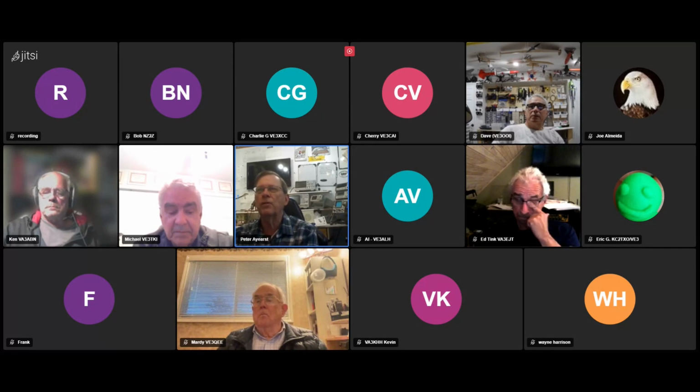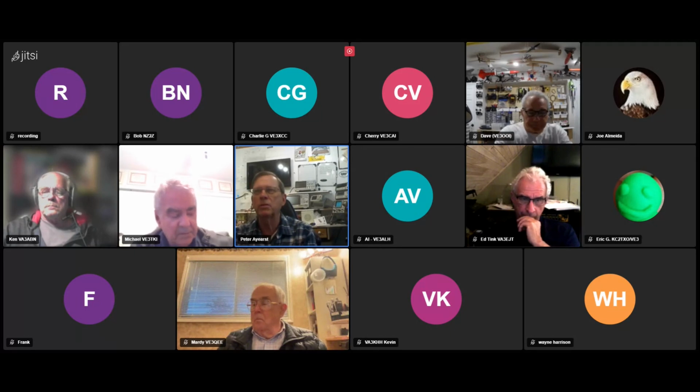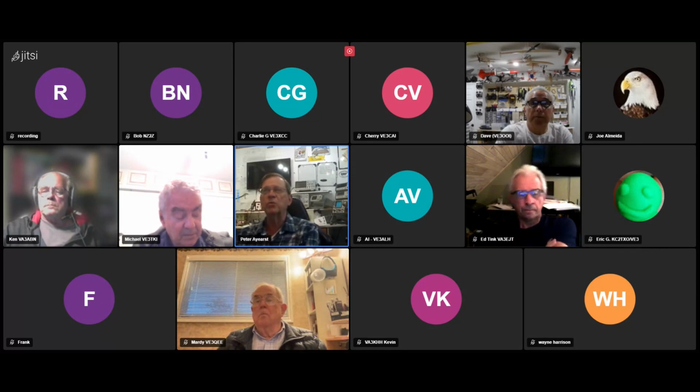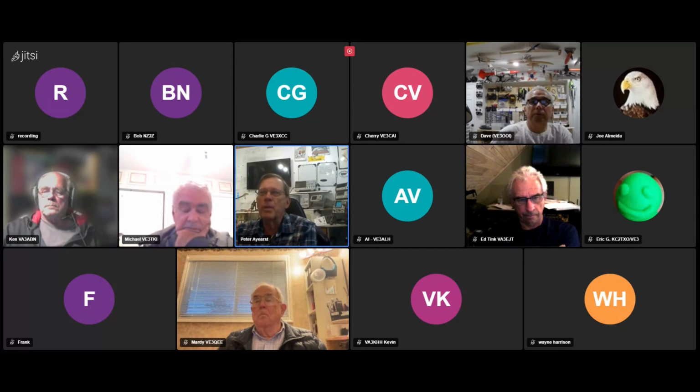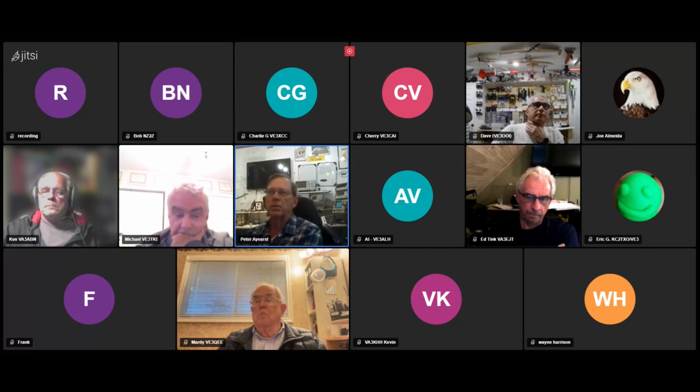So if you can simplify things by putting a lot of these dot measure statements in there, and have it spit out in your log or your Spice log, the data is right there. You don't have to do a simulation, move your cursors back and forth, and then make the notes yourself. You can do the copy paste and all that kind of stuff, and it's much easier and quicker.